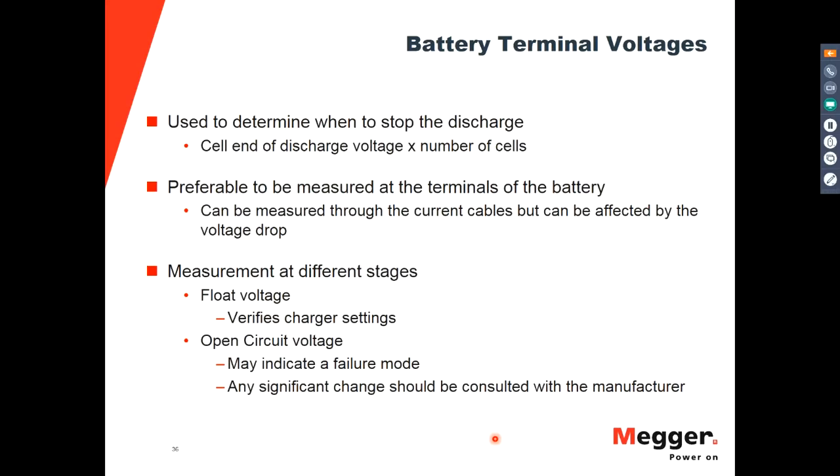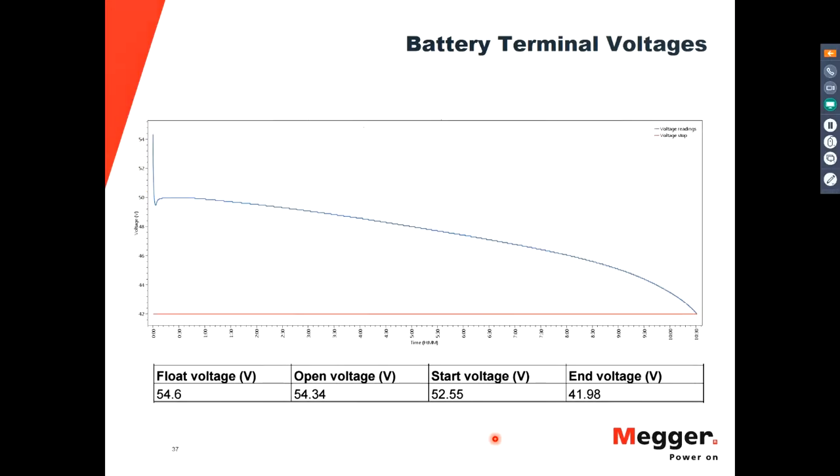Depending on the condition of each cell, the cells might drop a little bit or might drop a lot in voltage. And this is an indication that the battery might fail during the test. So you want to take some provisions for this to be avoided, or you can decide not to run the test because of this voltage situation.